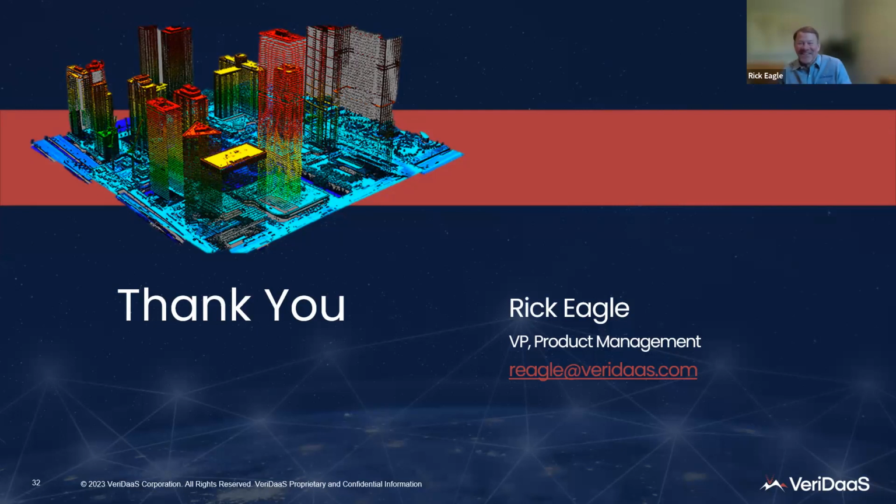Okay, I don't know if I'll properly answer this. We typically, if we're doing a project, it depends on who we're doing the project for. When we do DTM work and some of this forestry work for utilities, we're specifically doing it to that customer's specification. We do, though, deliver to counties and local agencies directly to the USGS QL1 specification for their DTM. So I believe half-meter spacing, all the water flattening, the level of extraction for the break lines. We follow the 3DEP specification when we're delivering to a state or local agency.